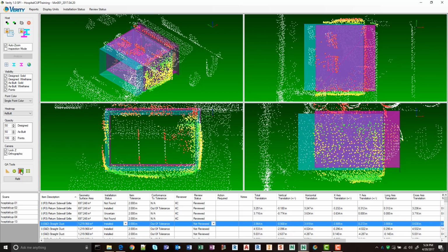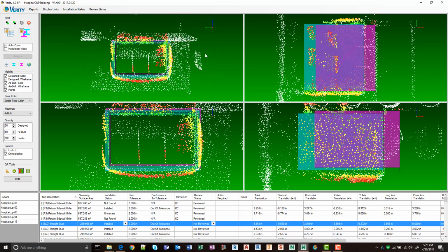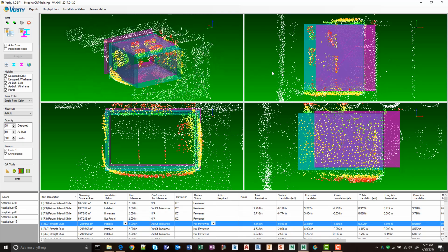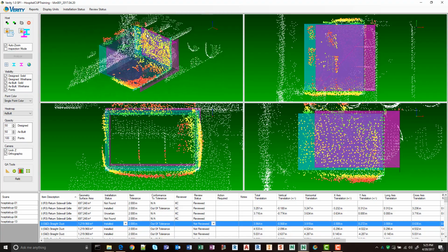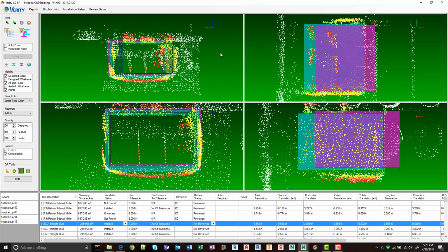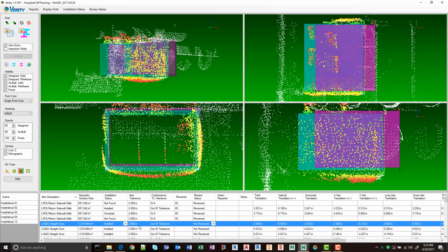So I'm going to, again, recalculate the heat map, and we can take a look. Heat maps are useful for things like this because if we've done a good job, we should see a pretty similar distribution of colors on all the different sides where the object's visible. And we know on the bottom it's going to sag a little bit. It's about 2 inches thick. And here we've got a 2-inch tolerance, and that means our heat map is going to go from green to red, and red is going to really be that 2-inch mark.